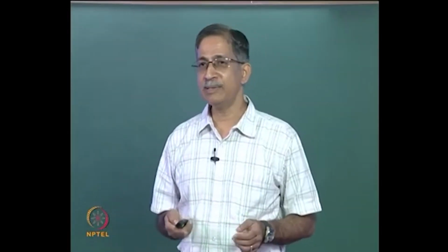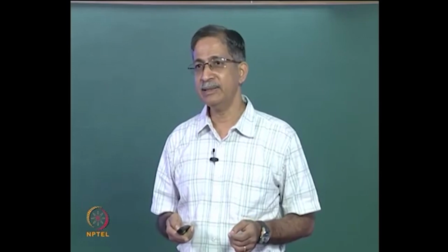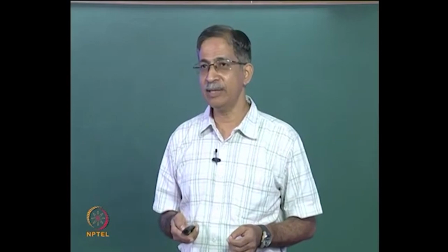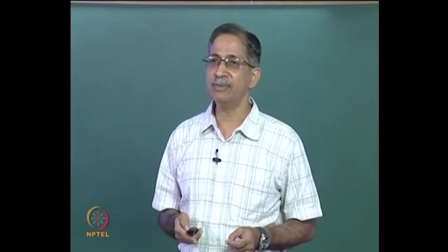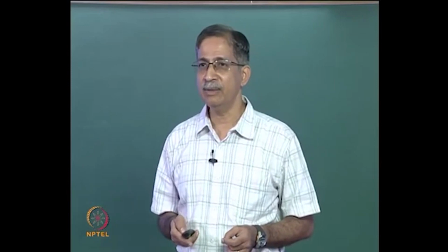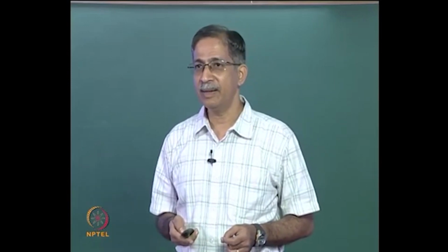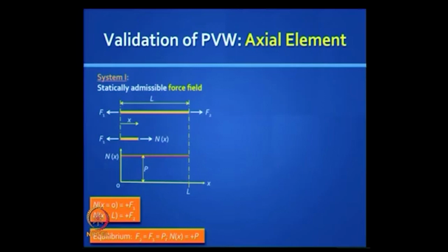And if you want to express in terms of boundary conditions, the axial force, the internal force at x equal to 0 must be equal to plus F1, and the internal force at x equal to L must be equal to plus F2, and F1 and F2 must be numerically equal to each other.